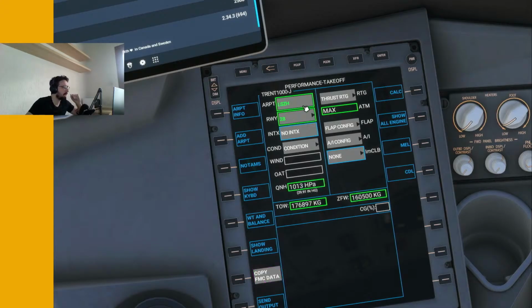Okay. So Zurich, runway 28, QNH, is it correct? No. QNH is 1014. Okay. Wind, it's 170, but I have no idea, unfortunately, how to import it. It's 4 knots, but it's crosswind. It's minus 1 knots of headwind, so I'm gonna keep it 0. I mean, it's not gonna make a lot of difference in this case. I guess it's mandatory, so let me set up 0 here. Yeah, 0 knots. Still, after years, I still don't know how this stuff works.